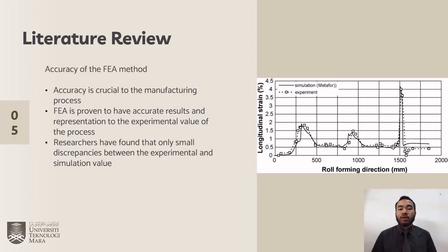The graph on the right shows one of the findings obtained by using the simulation. Notice that the longitudinal strain obtained is similar to the graph mapped using the experimental data. This shows that the FEA is relevant and can be implemented to predict the metal behavior.